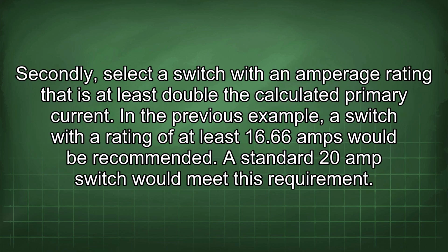Secondly, select a switch with an amperage rating that is at least double the calculated primary current. In the previous example, a switch with a rating of at least 16.66 amps would be recommended. A standard 20 amp switch would meet this requirement.